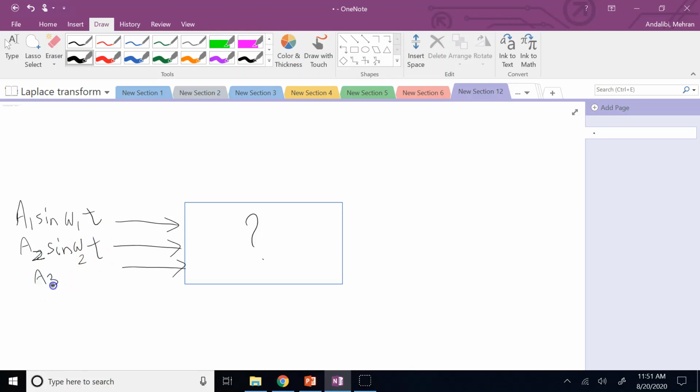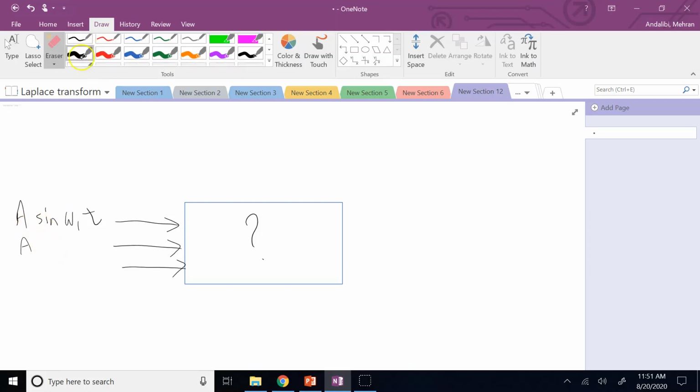So you change magnitudes. Mostly, more important than that, you change, even you don't need to have different A's, okay? You can just have different omegas. You don't need to change the magnitude really. So all you need is to change the frequency. So you give this, then you give this. So you keep changing your frequency, and in the output, you get basically here some B1 sine of omega 1t plus phi 1. So the magnitude will change and you get a phase shift.